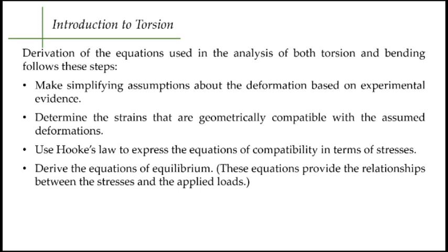Then two, use Hooke's law to express the equations of compatibility in terms of stresses, because although we will be encountering different geometrical compatibility equations as compared to strain, one thing that we really want to solve in these kinds of problems is the shear stresses, right?